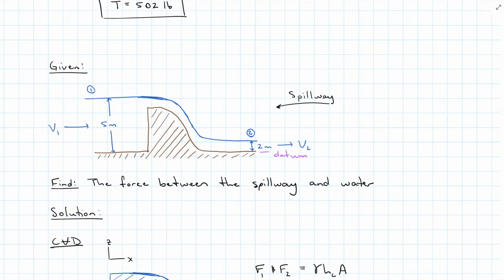Just a reminder, the hydraulic grade line is going to be that open water surface. Since this is an open channel, then the hydraulic pressure head and the elevation head are already at the level that they want to be. And then we have the energy grade line. That is going to be the velocity head higher.